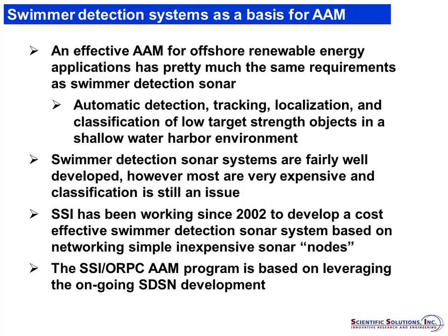So swimmer detection systems is the basis for the active acoustic monitoring system. It turns out that an effective active acoustic monitoring system for offshore renewable energy basically has the same requirements as the swimmer detection sonars that have been much more fully developed over the last 10 years or so, since 9/11.